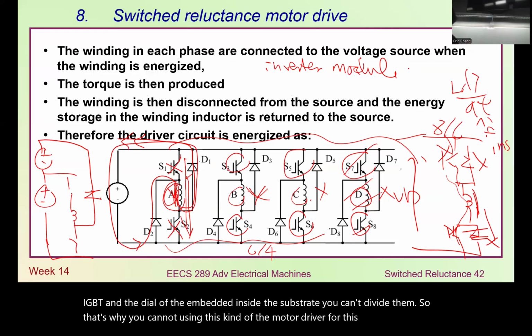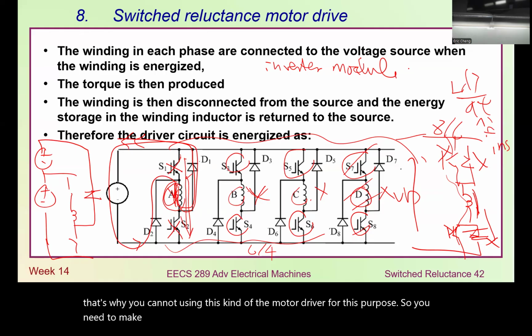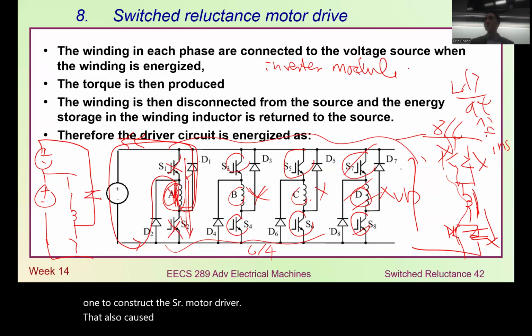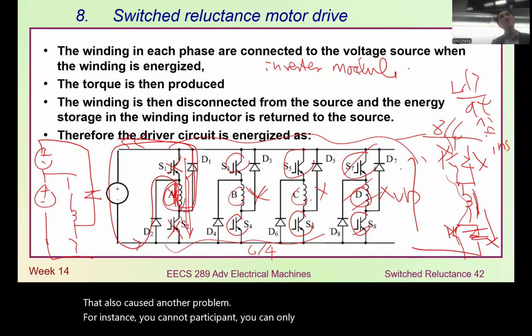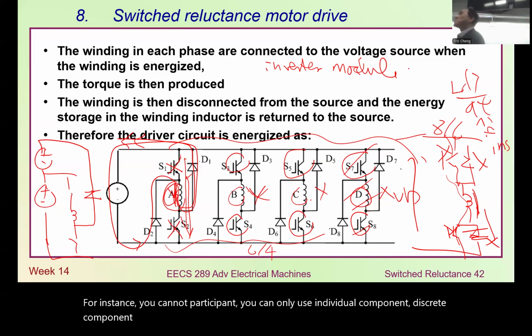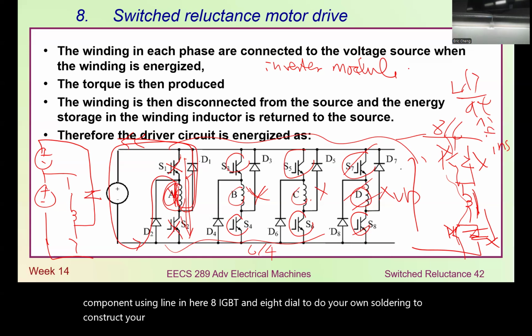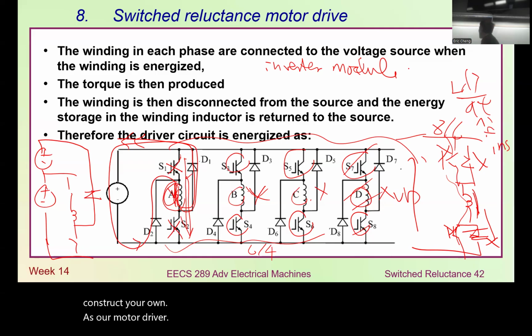So you need to make it deliberately by yourself, or maybe use a number of these to construct the SR motor driver. That also causes a lot of problems. For instance, you cannot buy this one. You can only use individual, discrete components, like in here, 8 IGBTs and 8 diodes, to do your own soldering to construct your own SR motor driver. That's really much more inconvenient.